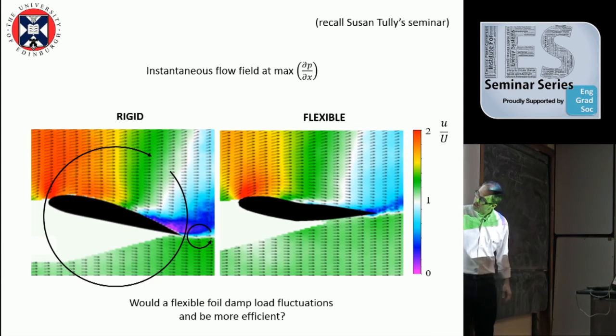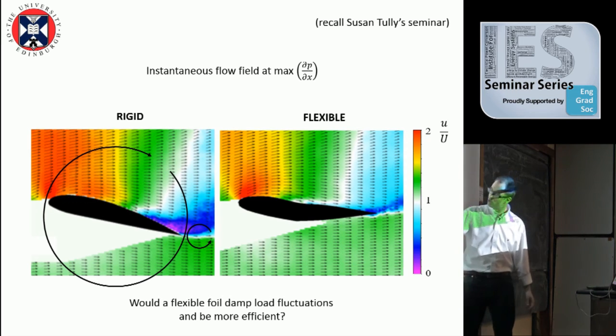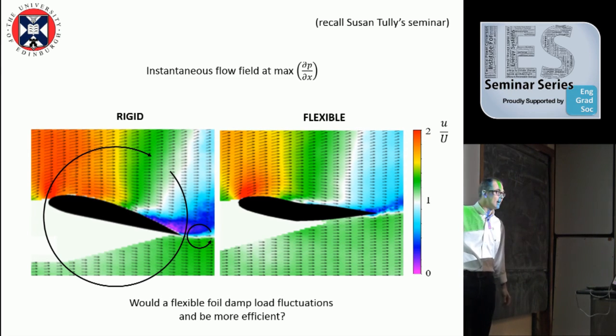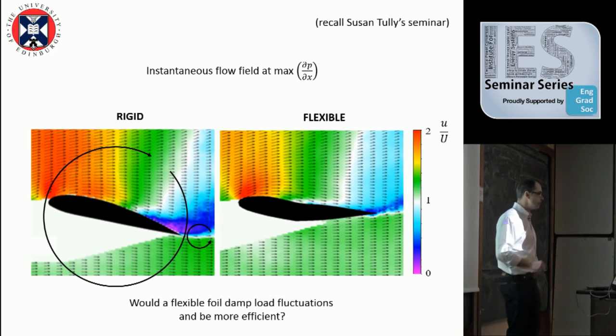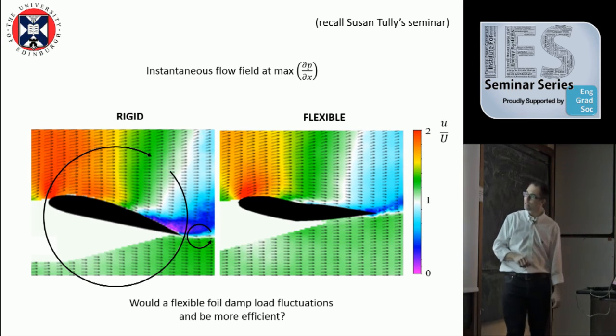But here, you're actually generating a trailing edge vortex. So you're actually generating a vortex which is rotating in the opposite direction. So because of this vortex, which is undesirable, this one will diminish the strength of your circulation, and so it will diminish your lift. So every time you generate and shed this trailing edge vortex, you have a drop in the lift. How can you prevent this?